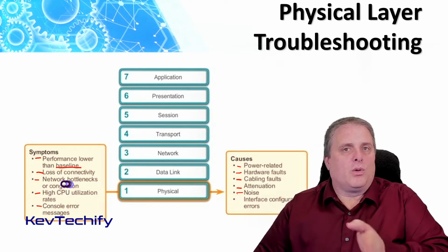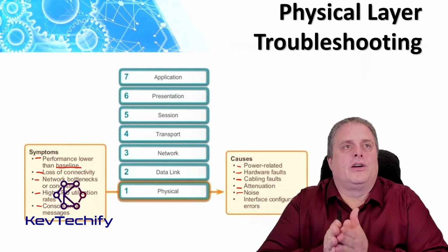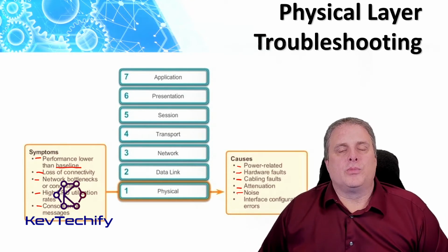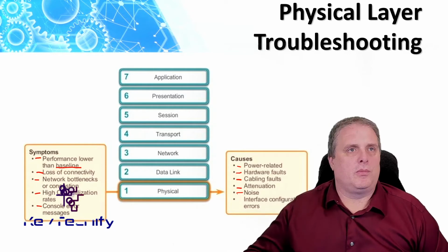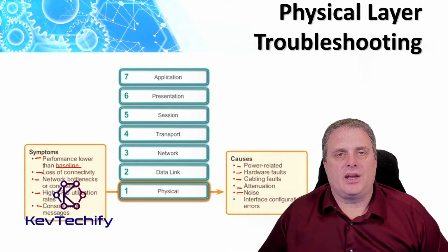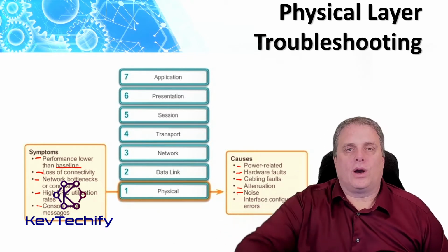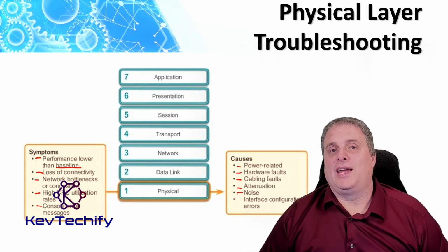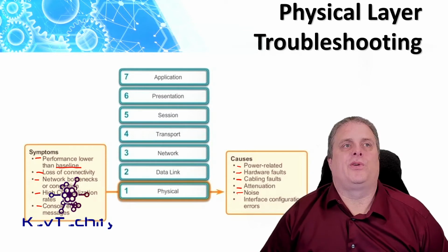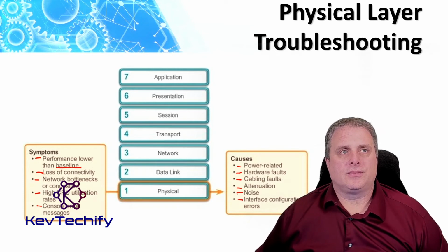If you run a network cable next to an electrical line, you're going to get interference from that. Large electric motors out in the machine shop are going to generate electromagnetic interference. FM radio stations, police radio stations. If you're looking at Wi-Fi, wireless phones that work in the 2.4 gigahertz, some microwaves cause problems because they operate in the 2.4 gigahertz.